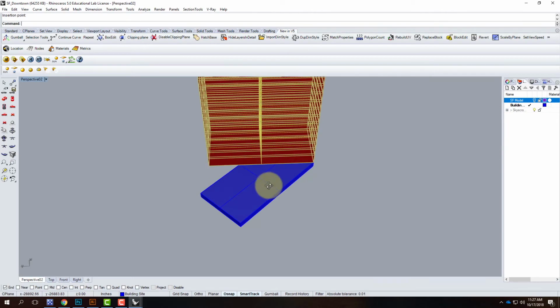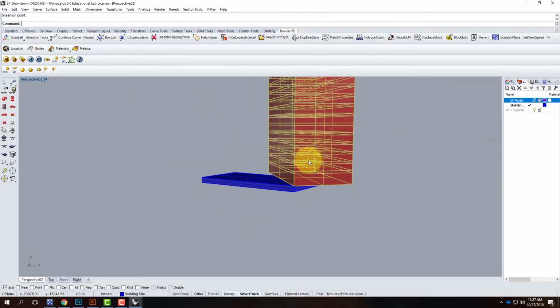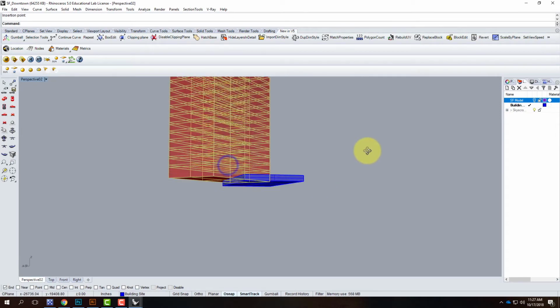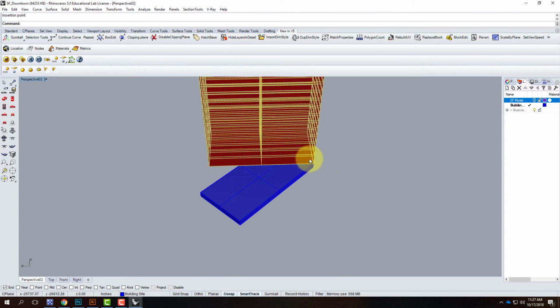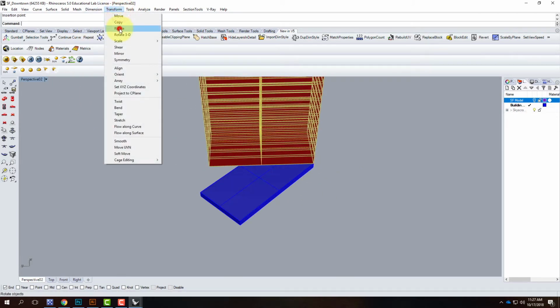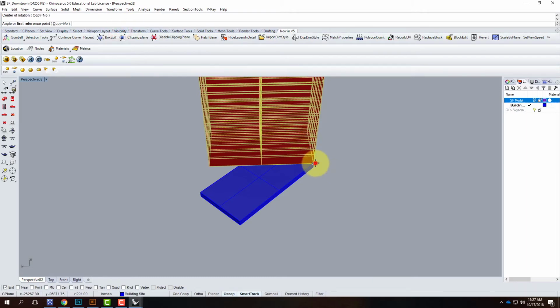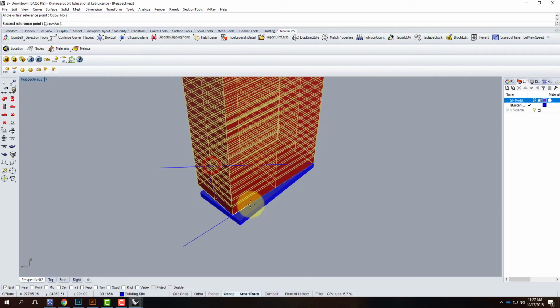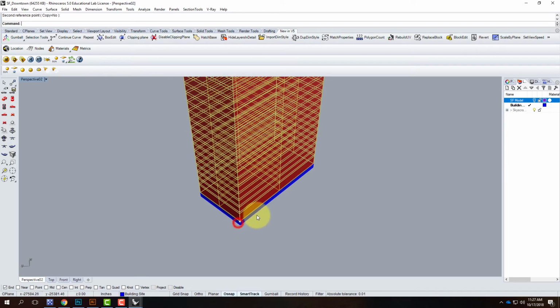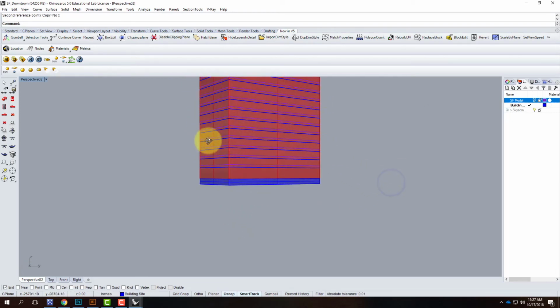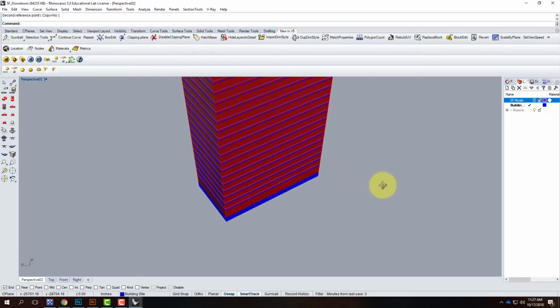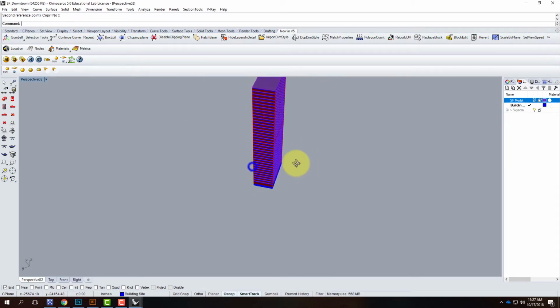Because Market Street is on a diagonal, this building needs to also be on a diagonal, so I'm going to have to rotate it after the fact. So I've dropped it in as a block, but then I will have to go up to Transform and then Rotate, or just type Rotate. And we'll rotate this so that it lines up. If your base is 100 by 200, it lines up perfectly. If it's not, it doesn't. You can work with it.